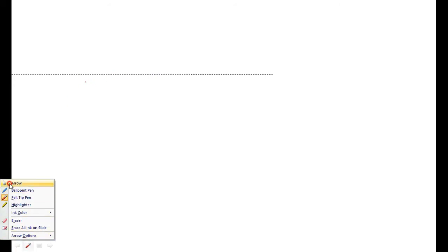I am starting by drawing a current IA, which I told you is making an angle of 36.86 degrees with respect to the reference. Suppose this is I. First I have IRA, because I know the value of IA and the value of RA, so I know IARA, that is the resistive drop. The resistive drop is parallel to IA.